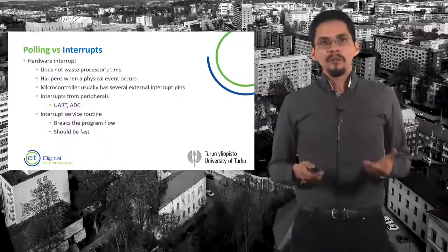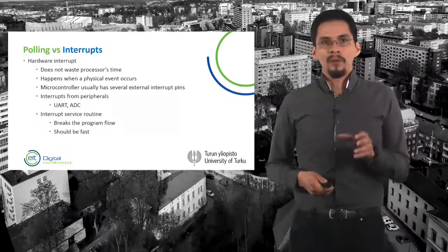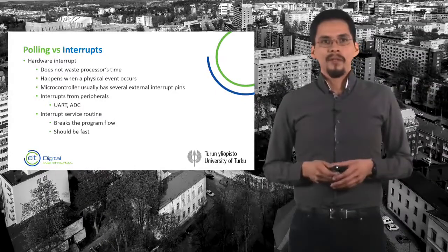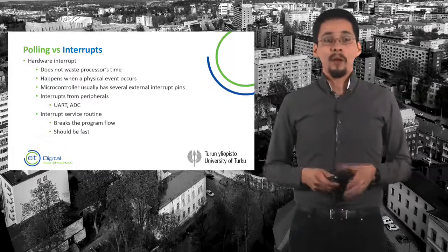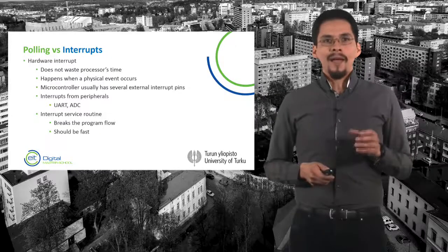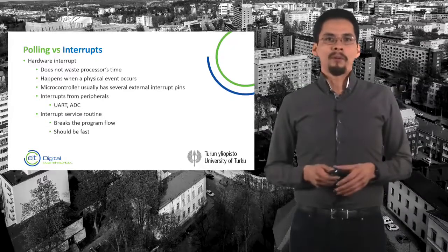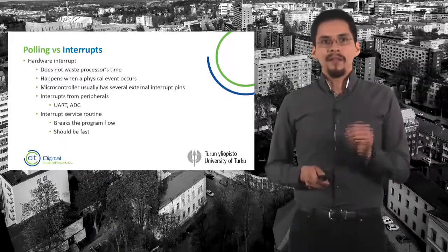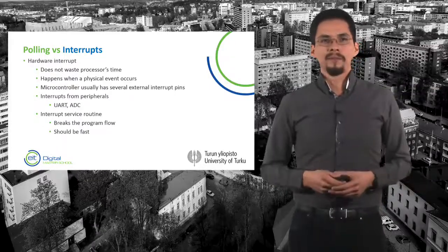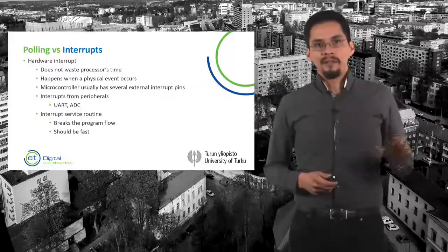So, is there a way to catch fast random events? Let's consider that we have a microcontroller as a tool for that. With the power of interrupts, it is possible to catch fast events and, what is more, to estimate the time when the event occurred. An interrupt is a hardware-based way to break the main flow of the program, which means this method is fast in the sense that the hardware reacts quickly to the event. Furthermore, it gives control to software to process the event.